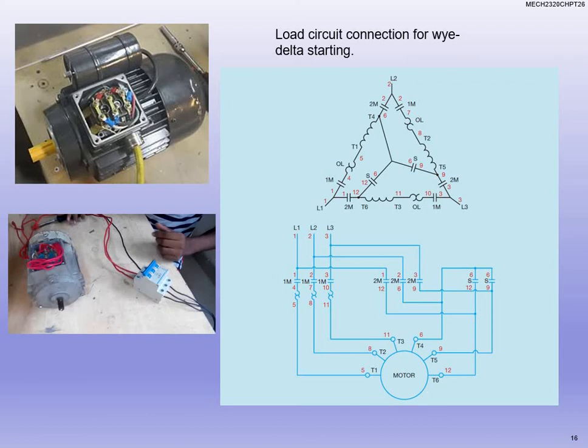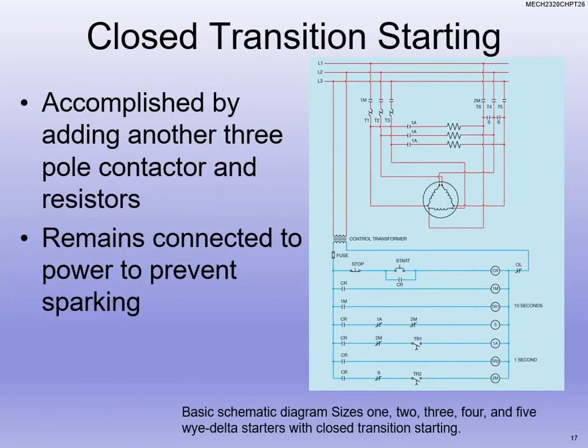And before, when I was talking about, hey, remember we can put the Y inside the delta. That's done for us at the top. You can kind of see how all the connections happen, where the contactors are, so that we make all those. Okay, this isn't something that you just blow through. You need to study it for a little bit and make sure that you understand it, especially when you're in the field wiring something up. Okay, so very, very important here.